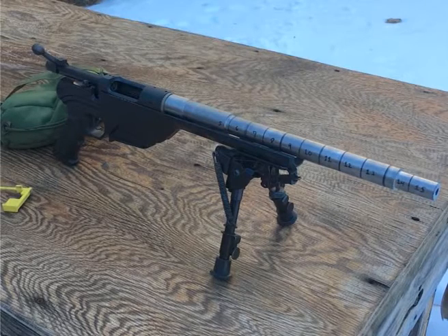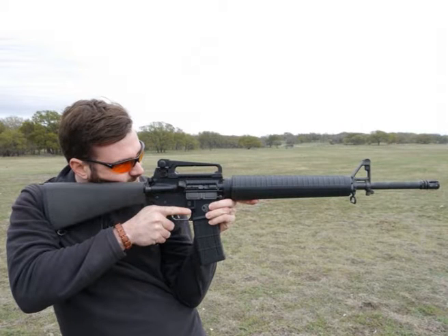To have an idea of the magnitude of pressure developed in a barrel, I will quote an example. A service rifle is expected to withstand a barrel pressure of 50,000 pounds per square inch, but test fires would be conducted with ammunition giving rise to a pressure of 70 or more thousand pounds per square inch.